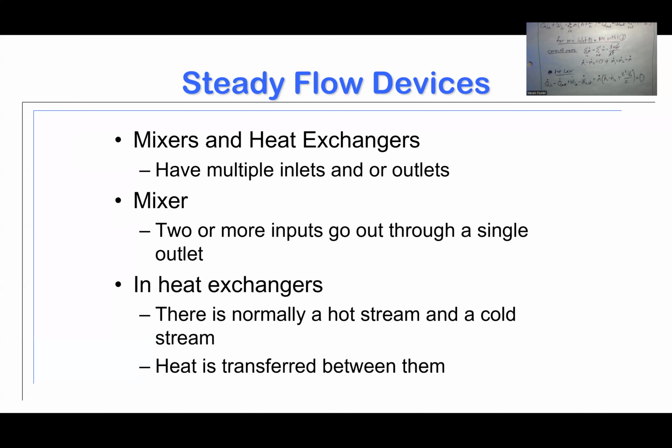A lot of times in food processing, we'll use steam kettles or steam jacketed devices where we've got a food product coming in and we need to warm it gently, but not really add anything to it. But what we can do is add a little bit of water to it. So we have a concentrated cooler product like soup or something like that coming in. We can inject high temperature steam into it. And that will, number one, warm it and number two, reconstitute it a little bit. That's a very simple, clean, gentle way of doing that.